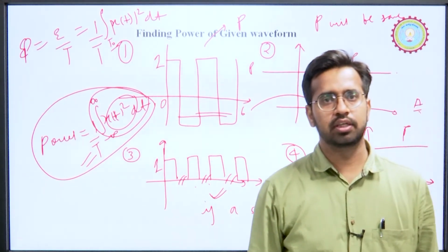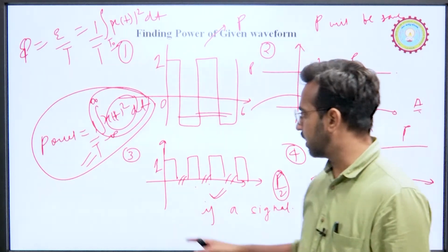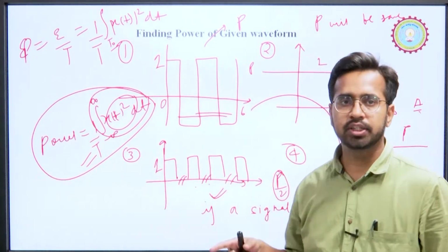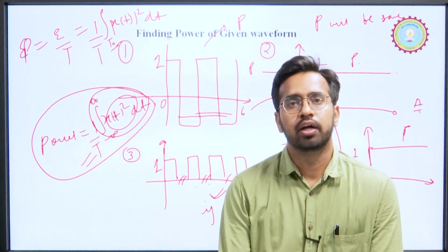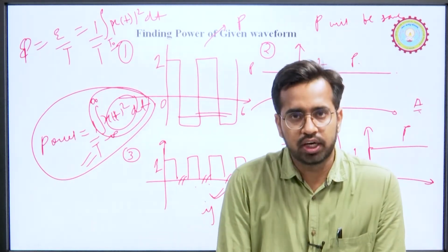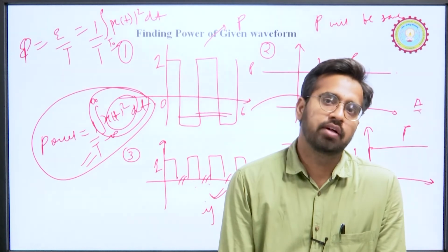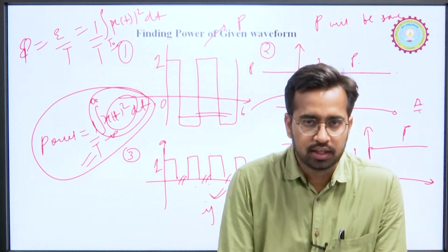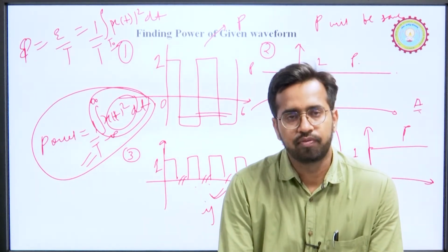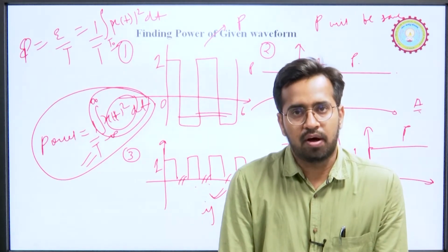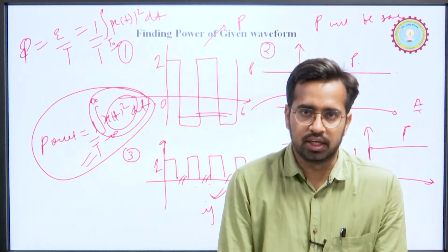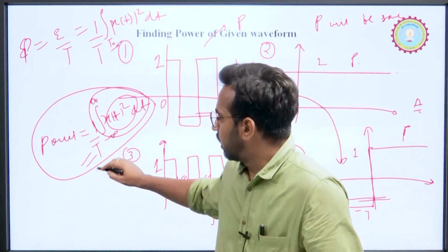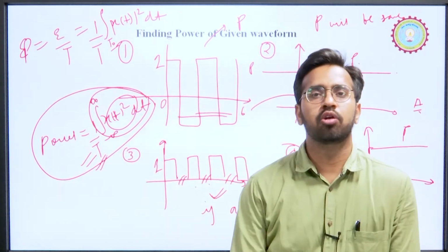See, what is the difference between energy and power signal? If we talk of the operation in energy signal, whenever we are doing time scaling, the value of energy was getting reduced by the factor by which the time was scaled. But in the case of power signal, the power of a signal is unaffected by doing any time scaling, because that same factor of time is also coming in the denominator.